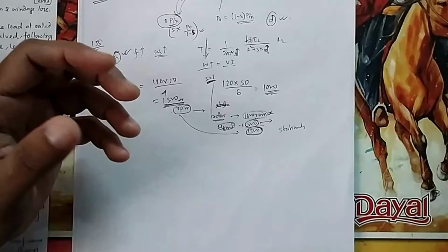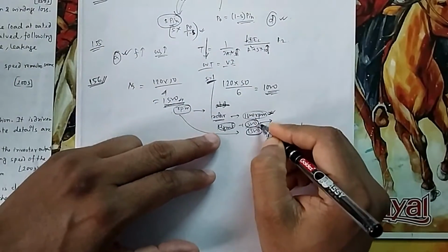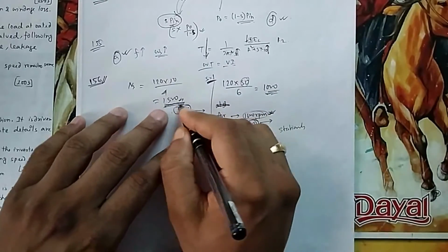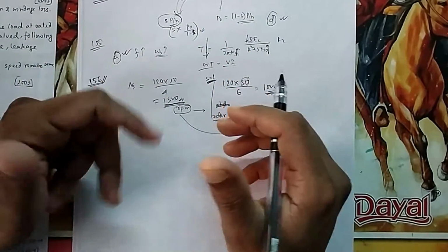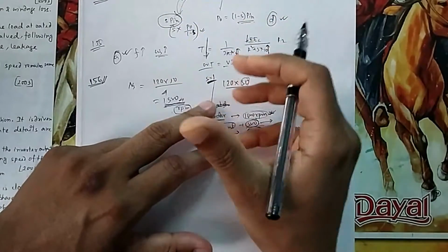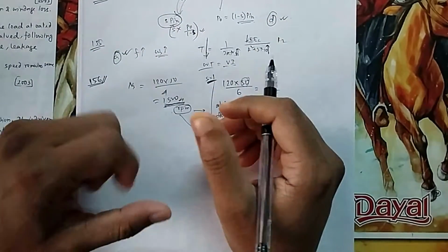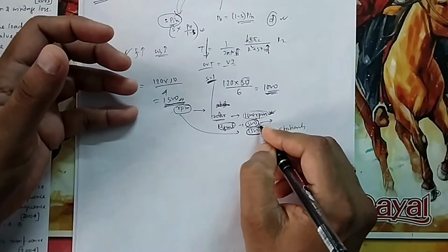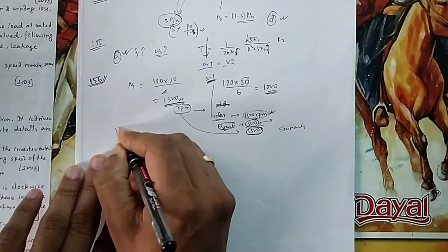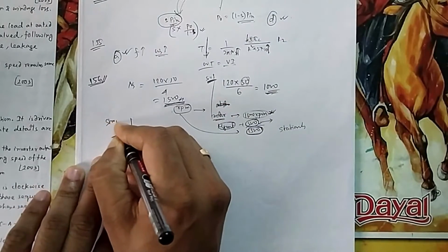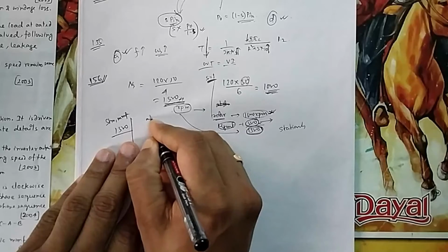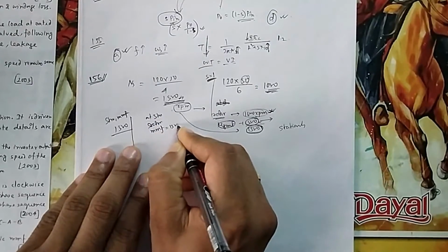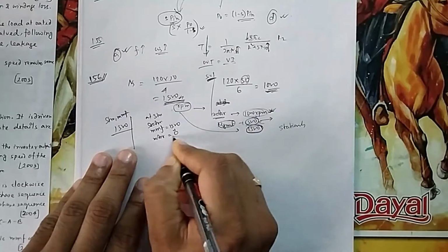Gradually, as it starts picking up speed, the slip will fall, so the rotor frequency will fall. So at the very beginning, both these fields should have the same synchronous speed, so that even if the rotor is not rotating, they can still get locked. Once they get locked, then gradually if the rotor starts rotating, that speed automatically comes down. So you can think of initially the stator MMF rotating at 1500. At the starting the rotor MMF should also rotate at 1500 and the rotor's individual speed is 0, so the total is again 1500.